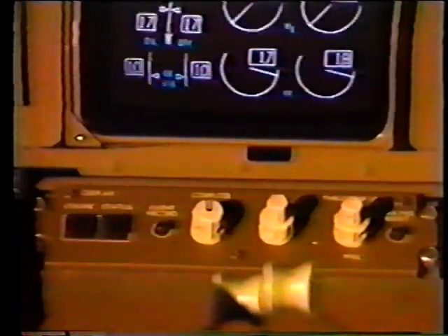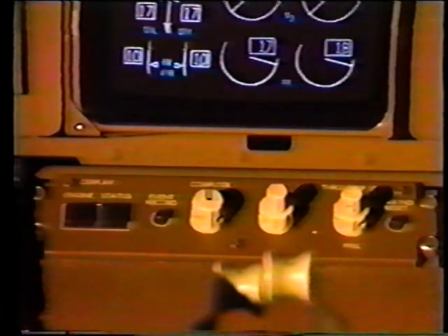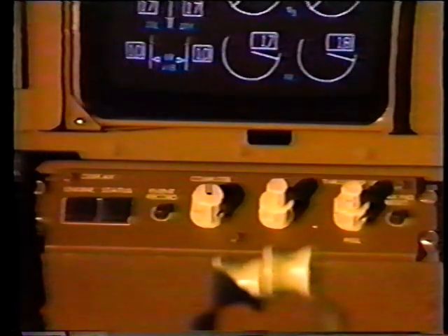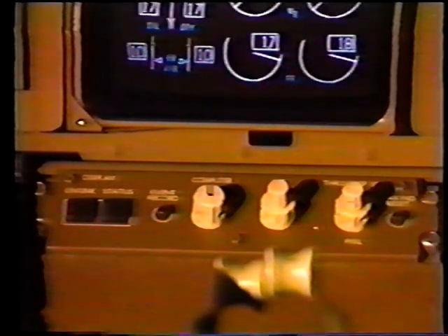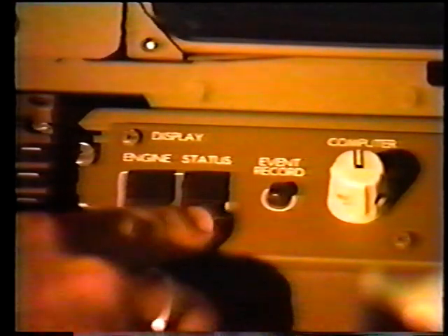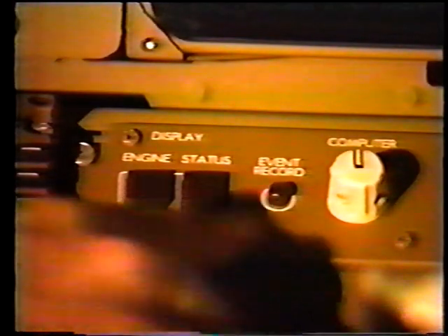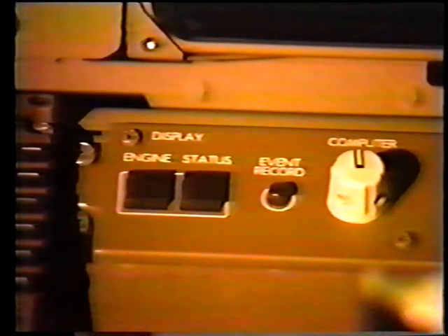Below the CRTs, located on the center control stand, is the pilot's ICAS display select panel. This panel controls the functions and displays of the CRTs. The engine and status switches control the secondary engine data and status data normally displayed on the lower CRT. The event record switch is used either in flight or on the ground to store maintenance data in ICAS memory